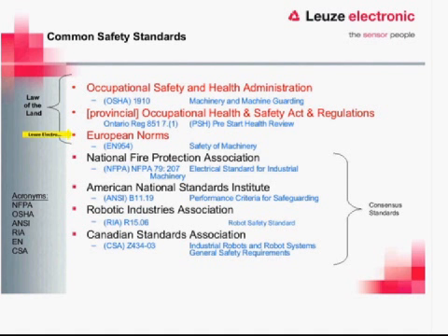This is a good one to look at because in the future, most of these safety regulations are all going to be standardized, and they're most likely going to be going towards closer to the European norms than what we do here at OSHA. And we can see that in some future webinars we'll do. You'll see the difference when we do just something simple like a safety distance calculation, how different it turns out to be if we go by ANSI RIA, or if we go by European norms, or if we go by OSHA. They all come out to a different distance.